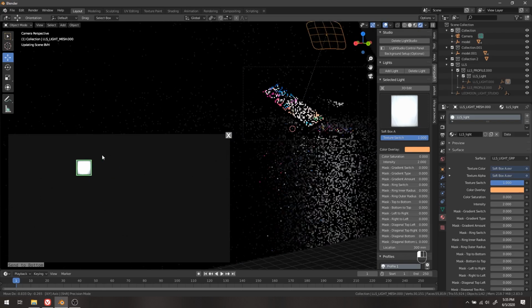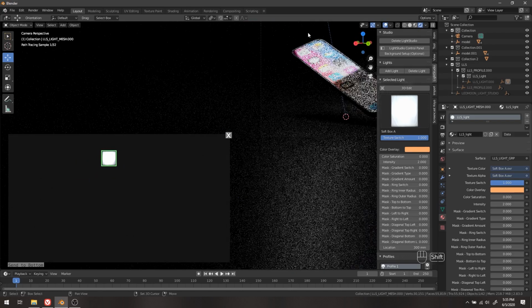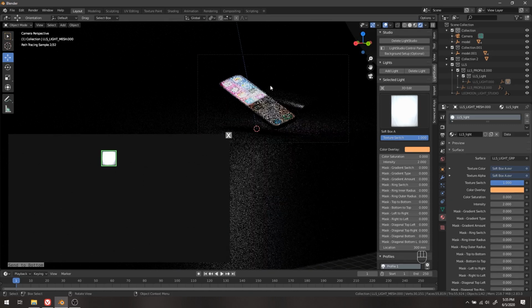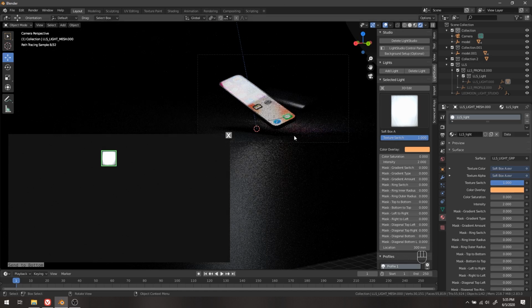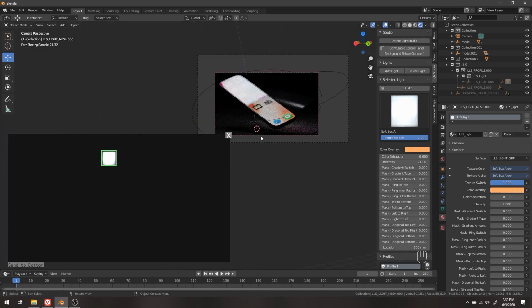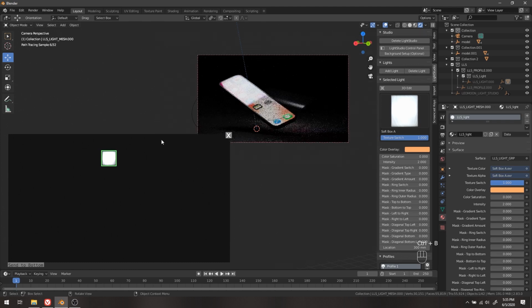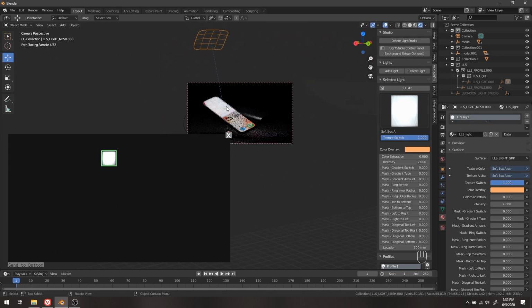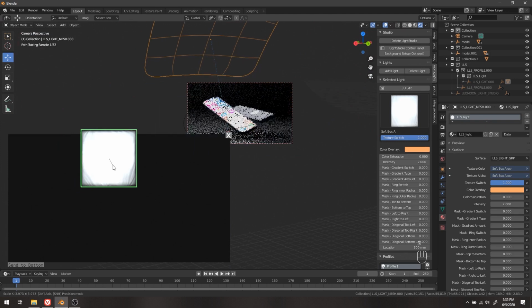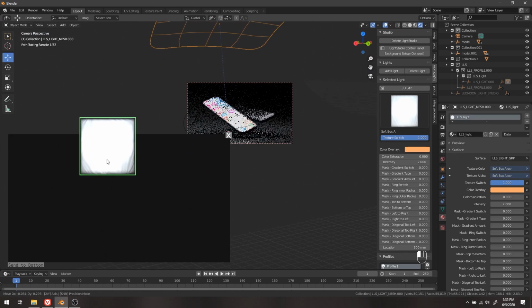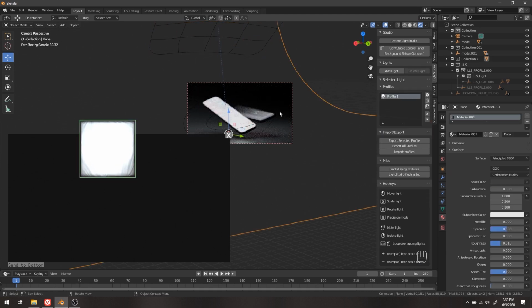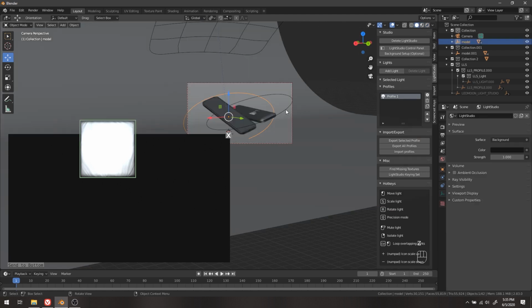So I'm going to start by giving this a little backlight, again with the camera view. In order to take some stress off of your computer, if you hit Control and B, you can select a region that it starts to render in. I just select the whole entire camera region, but that way it's not rendering outside of it like it was previously. All right. So I'm going to scale that up to get a better idea of where it is. I'm going to give these both a more dynamic angle by selecting them.